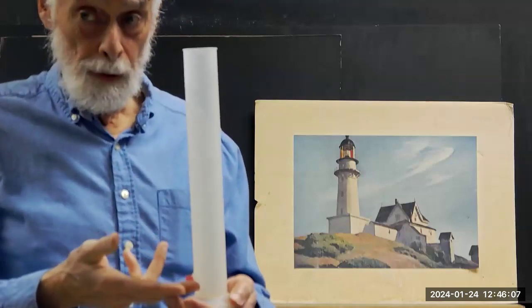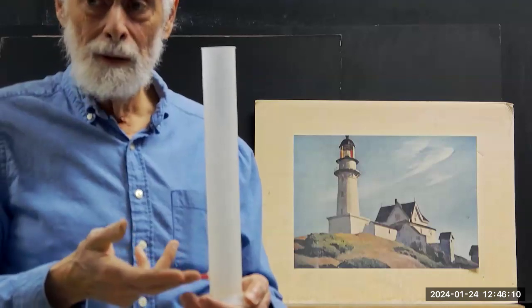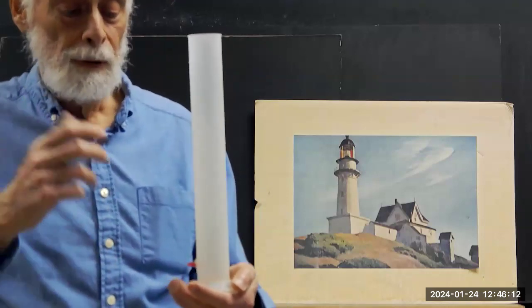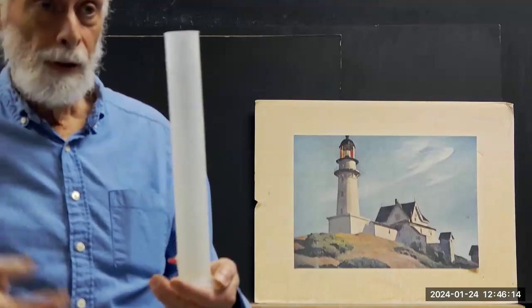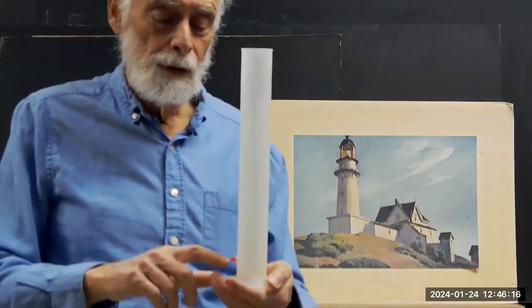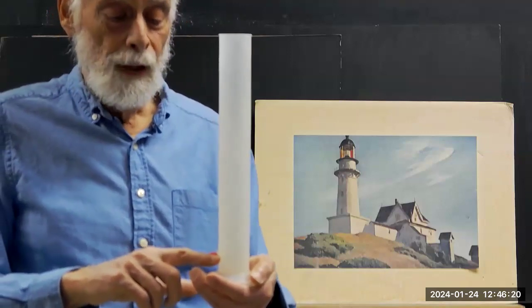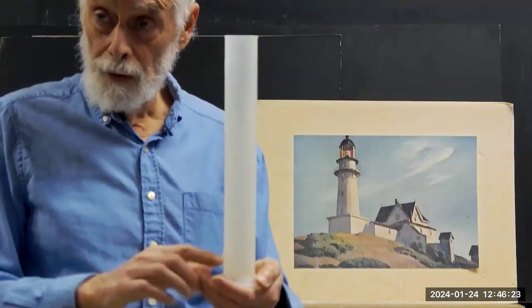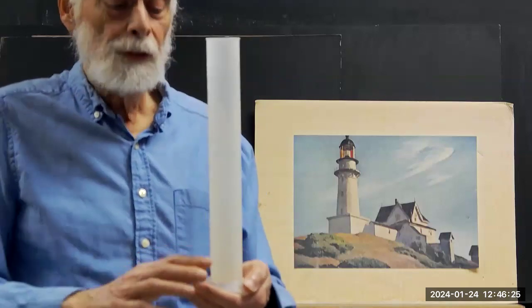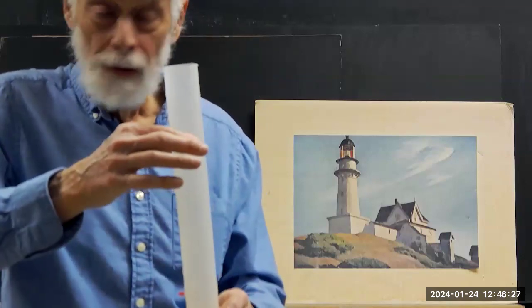How do we get the pressure down here? If you're watching, you should probably stop every time I ask a question and think about the answer. To get the pressure down here, we divide the force exerted by the water down here by the cross-sectional area, because it's the pressure down here that holds up the water above it.